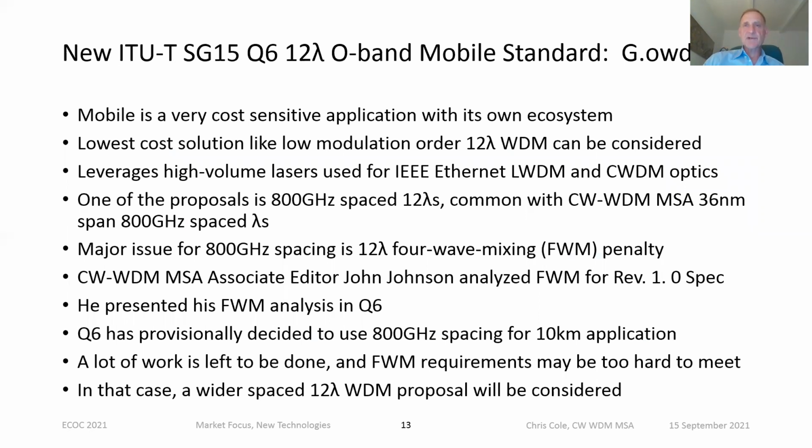There's an associated development. I'm sharing this with you to show you that there are many people looking at high wavelength count, O-band, datacom-like applications. ITU-T Study Group 15 Q6 is working on standardizing a 12 wavelength O-band mobile standard. It's called CW-WDM. And as everyone knows, mobile is very cost sensitive and it has its own ecosystem, so it has the luxury to define an optimized solution.